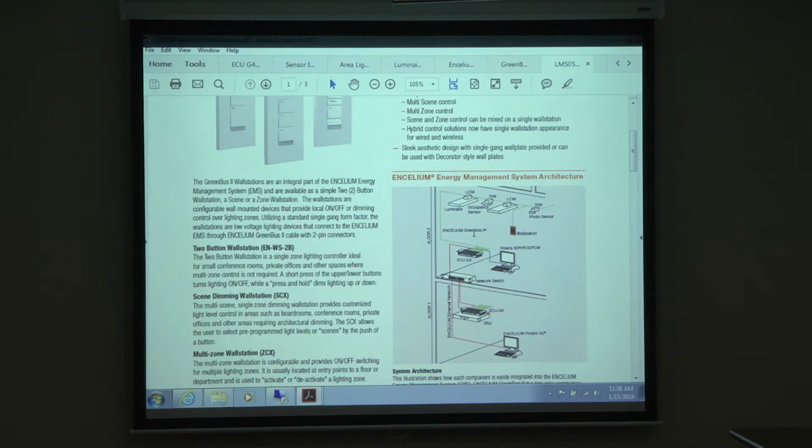The ECU processes the information, and then you ask, how does it know to come back to this room, right? In the program, you create a zone, for example, a zone or a room, and you link devices. So you say, okay, this sensor is linked to this room. This switch links to this room, right? So that's what the software system knows now. And the ECU sends the command back to the modules in the room. Say, hey, modules, close. Once they close, click, lights on, right? And that's pretty much what's happening. Happening real fast, but that's what happens, right? Press, back to the ECU, it processes, sends it back, and it turns on. It happens real quick, right?